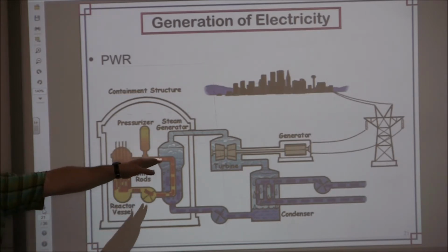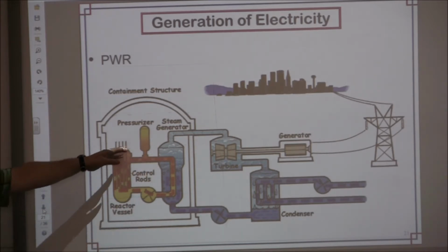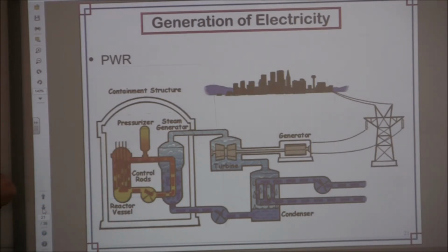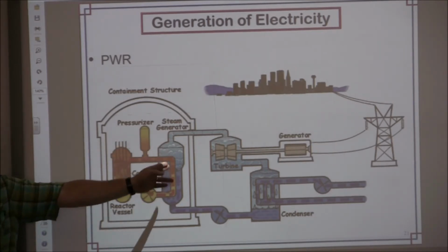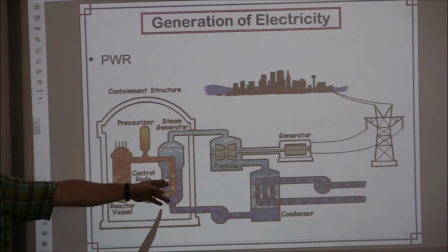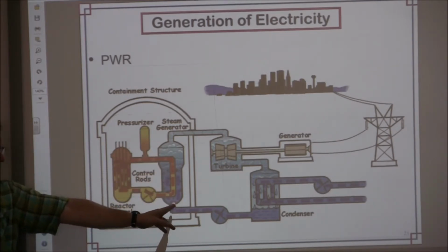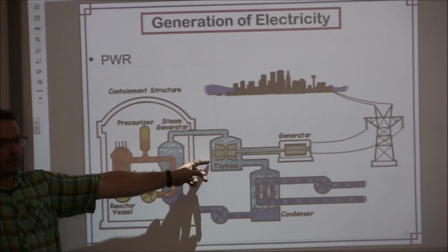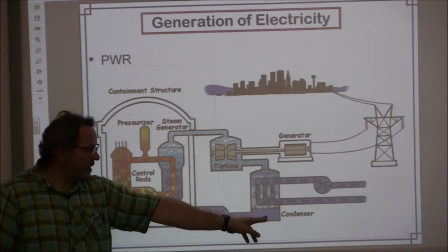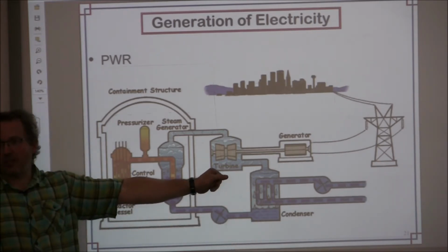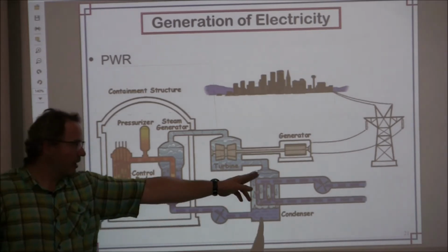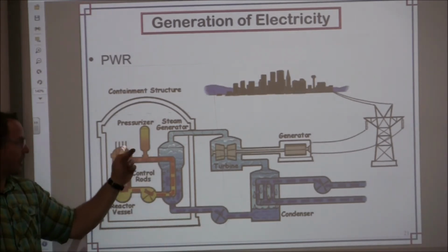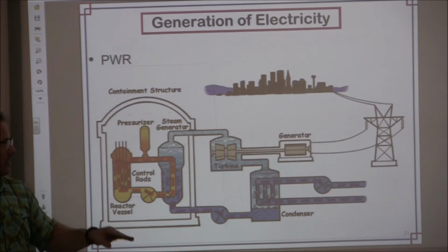The pressurizer maintains that 2250 psig, so this is a very sensitive device to maintain pressure. We run to our heat exchanger. We run a secondary system, not in contact with the primary system. Water here, steam to the top. Steam generator steam goes to our turbines. And then under here is the condenser, which is under a vacuum, to try to extract as much energy as possible. Now it's cool water, we pump it back to the steam generators and we do the process over again.